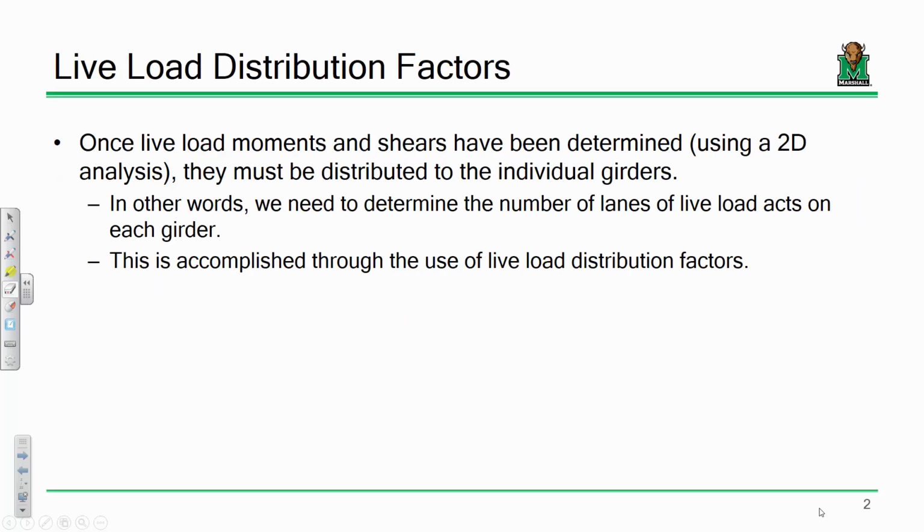I'm kidding. But live load distribution factors conceptually are a very simple, straightforward tool, but they are incredibly useful. I think there's plenty of room for improvement in terms of the ones that are currently in the spec. I think we could do better. There is always a healthy balance between coming up with better equations, but also coming up with equations that, while they might be better, are also more complicated.